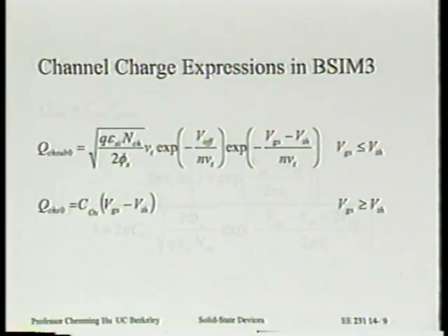These days, people want the SPICE prediction to be within 5% of what they get in the silicon. And in fact, even that is tightening every year. They really want 2% accuracy. So everything you have to model very accurately. All right.